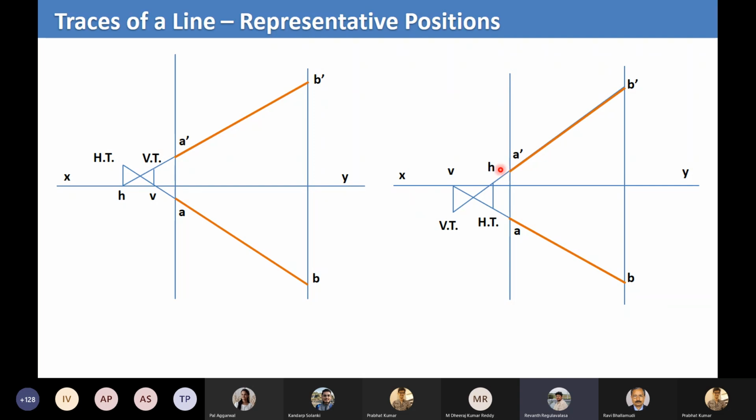So this is step 1. And there is the top view AB. Now you extend this top view AB. It will intersect XY at a point which is nothing but V. Now we draw projections from V and H. You just draw completely vertical lines, no problem at all. Those are the construction lines. You can draw them as long as you want.